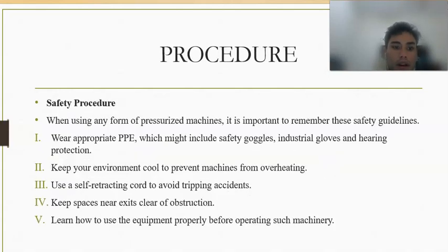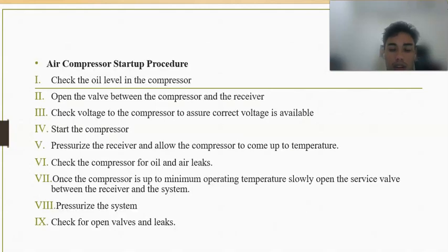For the procedure part, there is a safety procedure that we need to go through before we start the air compressor. We must wear appropriate PPE and keep your environment cool to prevent the machine from overheating, and also keep space near exit clear of obstruction if any accident occurs, and learn how to use the equipment properly before operating such a machinery.